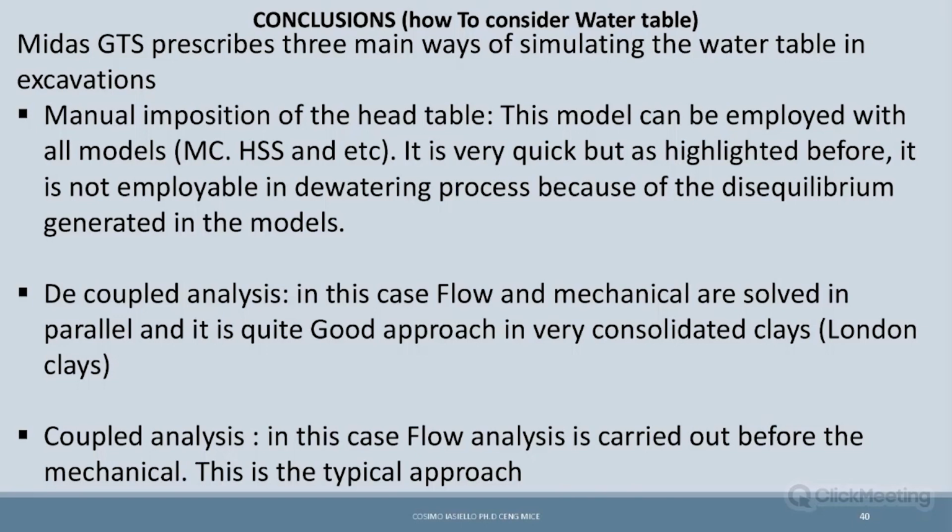Okay, Damian, does MIDAS GTS have the issue with small strain overshooting in the HSS model? No, no. This also can be corrected in your analysis control, in your simulation. For example, let me just check. I can open one case.